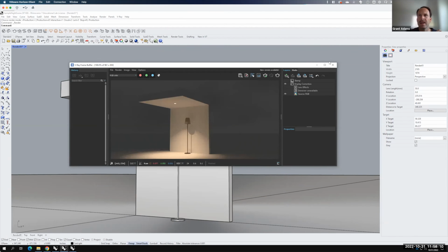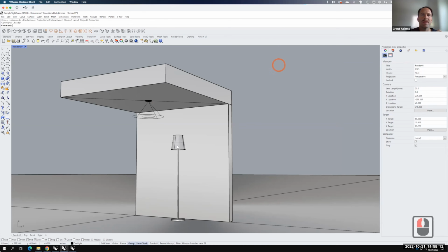Okay. So now that I have that in, let's install a light. Well, in this scenario, our basic spotlights aren't really correct because the light needs to go in all directions. So instead of using this basic spotlight tool, we're going to use this one, which is called the point light tool. So we can go ahead and click on the point light tool.